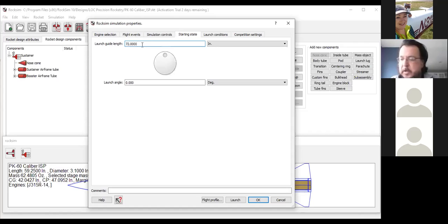Certain parameters come out of that 6-foot rail. You can change the launch angle of your launch rail. We don't recommend it. Leave it at 0. The Tripoli people will sometimes tilt the rail during a launch to compensate for wind a few degrees. But we won't allow you as a team to choose which launch angle you want. So just simulate to nominal, like 0.